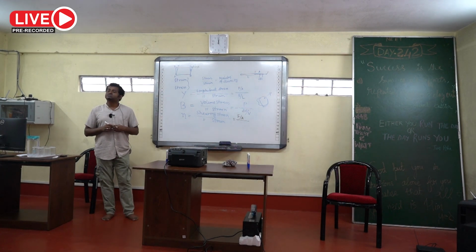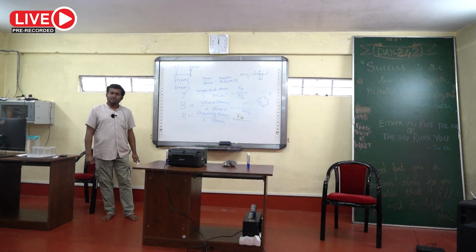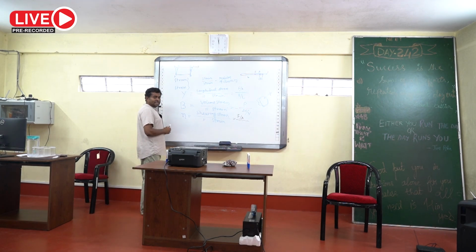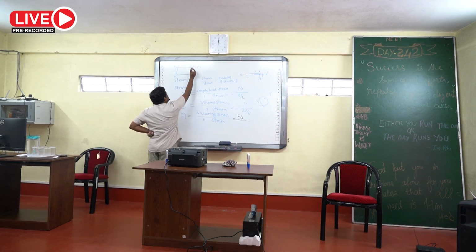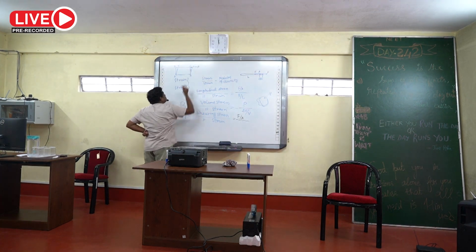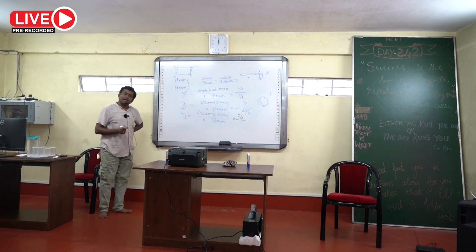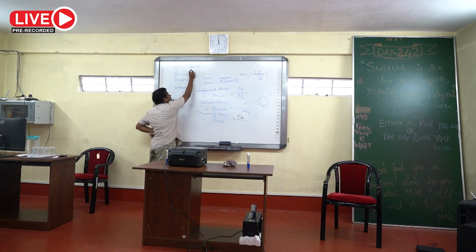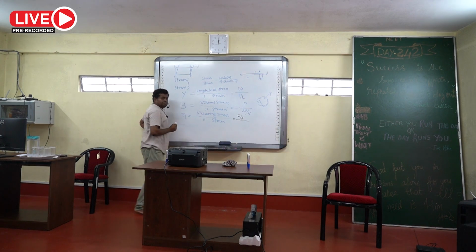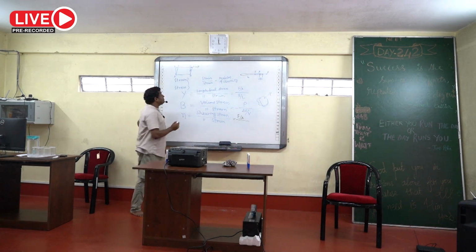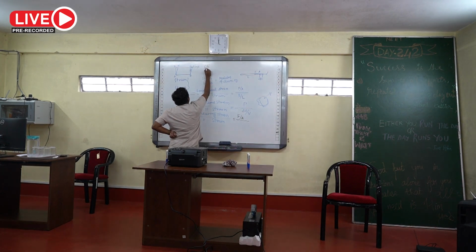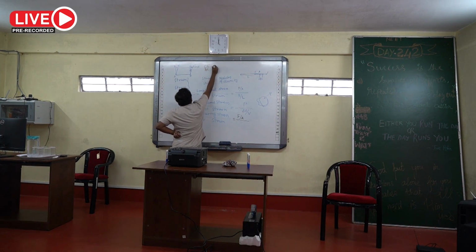Now what is shearing strain? That we have to calculate. See, what will be the change in this dimension? C prime, and what is the initial length? This one, BC. So if I calculate C prime divided by BC, that will become tan theta.